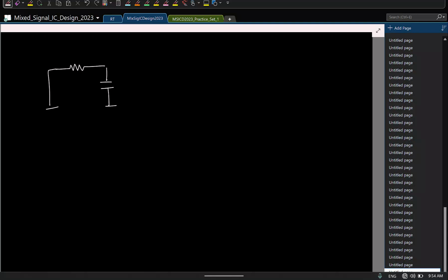Again, to model the noise, I'll assume that I have a voltage source Vn that generates noise. So this has a power spectral density 4kTR. And let us say I'm interested in the continuous time voltage Vout of t now. So what is the output power spectral density in terms of the input?